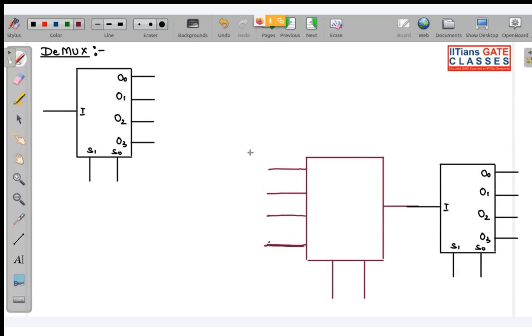So we had 4 transmitters over here and 4 receivers. Now with the help of this mux and demux, suppose I want to transmit from transmitter A to receiver C. This is receivers A, B, C, D, and this is transmitters A, B, C, D. So I want to transmit from A to C. What I will be doing is simply putting 0, 0 over here and 1, 0 over here. Now you can see, for connecting any one of the transmitters to the 4 receivers one at a time, I am requiring just 1 kilometer of wire.